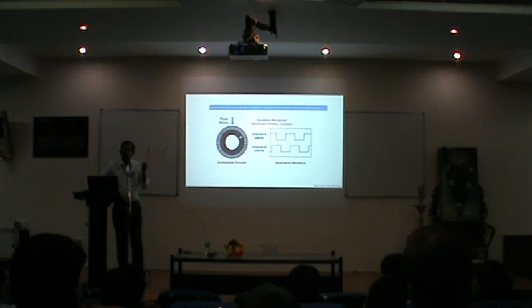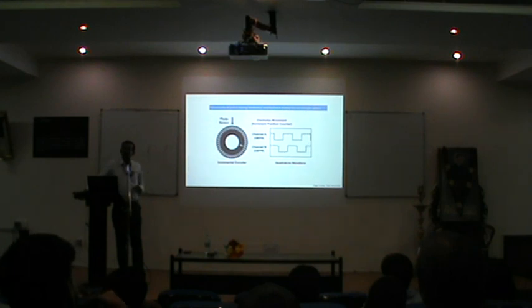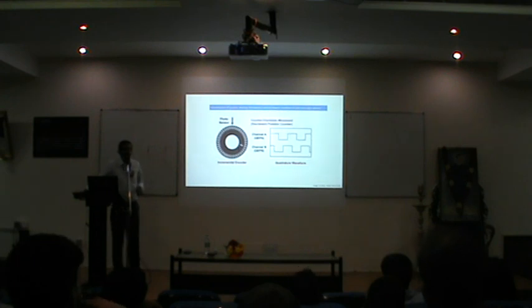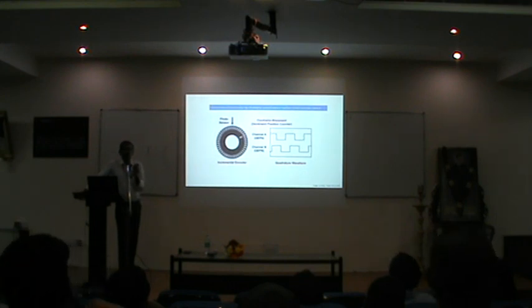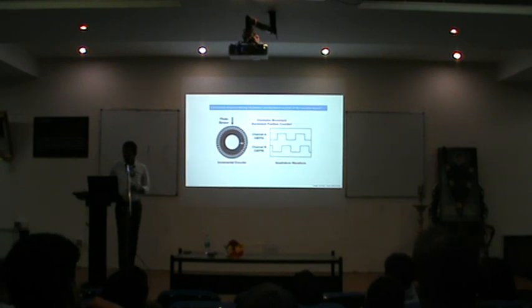Why is direction required? In your FOC algorithm, if you have gone through it, you will see that based upon the direction you will be determining certain coefficients and then you will be controlling your inverter. So obviously direction is an important thing. If you look into certain motor control applications like your PMSM or BLDC or perhaps your simple servo motor, you will be requiring the position information also. Those position informations can be obtained by looking into these pulses.